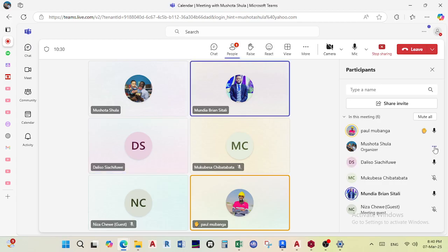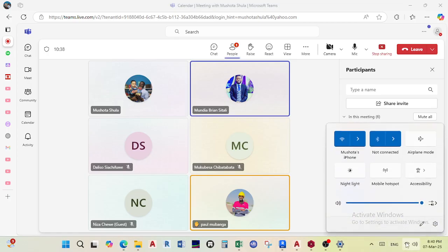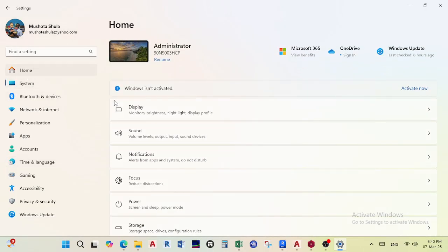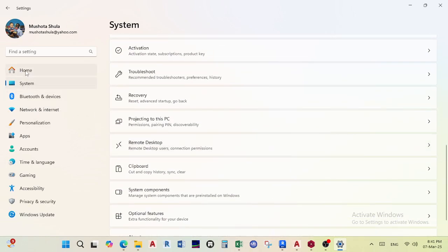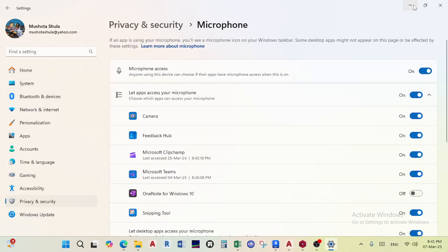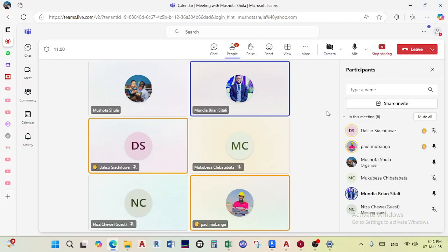So the reason why we can't do 233 meters continuously is that it's not feasible, it's not workable, unless you mobilize maybe 100 concrete pumps, I mean, not mixers, concrete pumps, and concrete is flowing in rapidly so you're able to pour the whole thing monolithically.